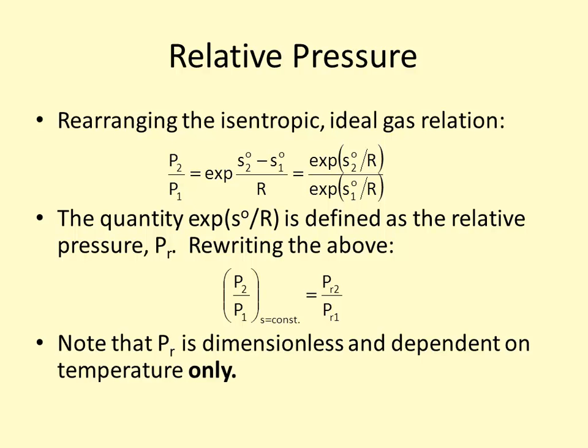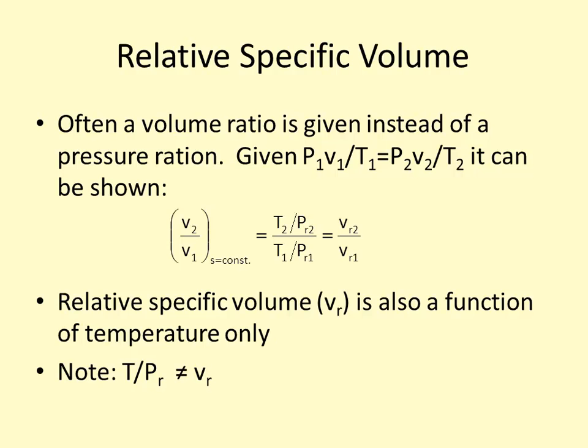If you look in there, you can see this P sub R is a value. And again, this is another way: if we didn't know the final pressure, but we knew the initial pressure, we could look up this PR1 on the table, find a final enthalpy, then use the final enthalpy to look up PR2, and back out the pressure from that. So it's another tool we have available to us.